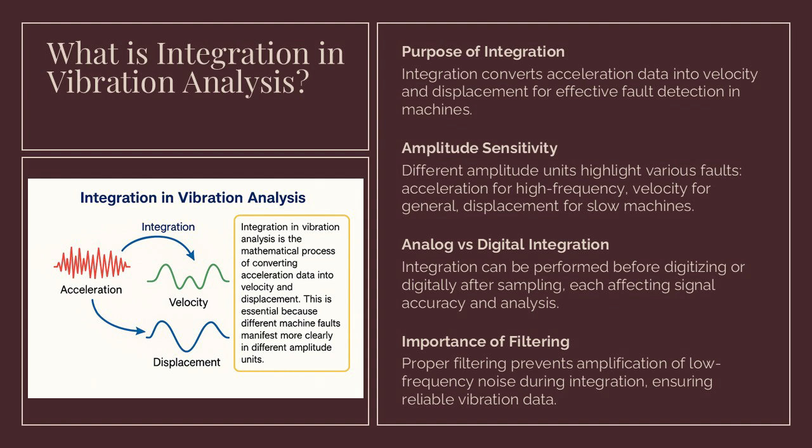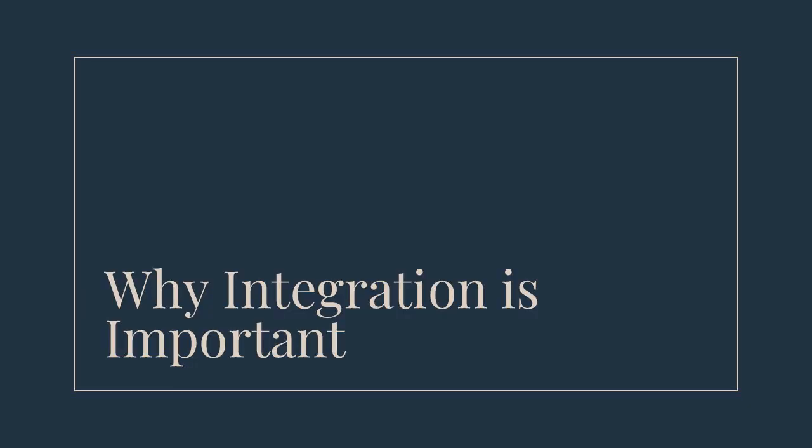Integration can be performed either in analog form before digitizing the signal or digitally after sampling. Understanding integration is critical for analysts because improper application can distort data and lead to incorrect diagnoses. The process involves dividing by frequency during conversion, which can amplify low-frequency components if not properly filtered. Therefore, integration is not just a mathematical step but a diagnostic decision that influences the clarity and reliability of vibration data.